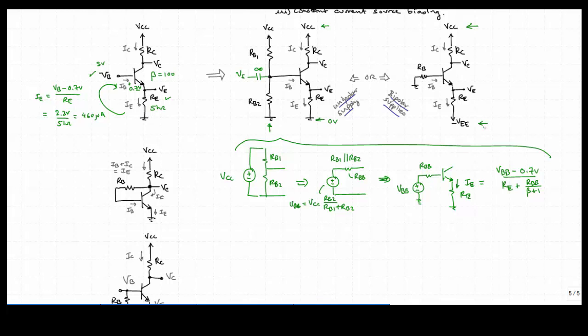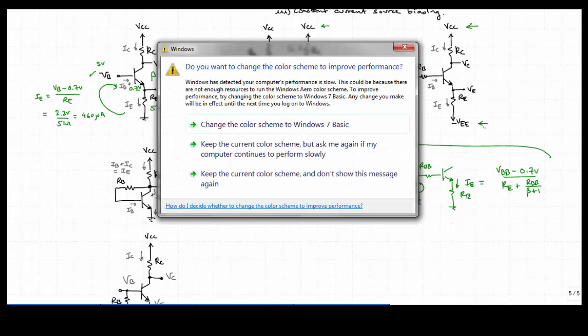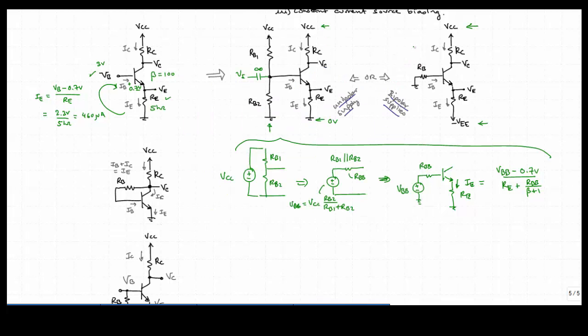Now you could have a resistor divider, RB1, RB2, that would connect between VCC and minus VEE, but that's typically not necessary. So I can write straight up by inspection now the emitter current. Again, we're going to go around this loop, and we're going to look at all of the voltage that is driving current to go in that clockwise direction, in a positive IE direction. And we will have